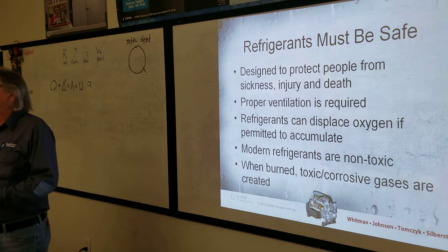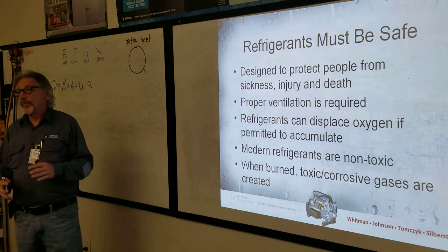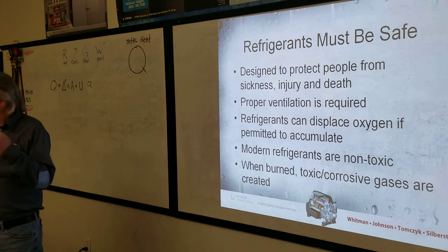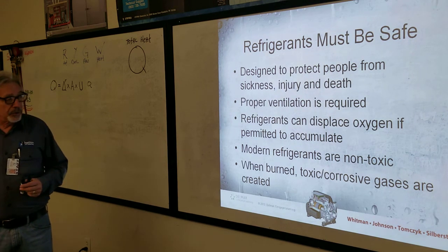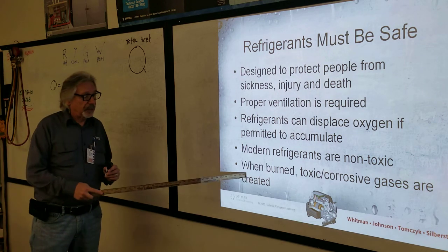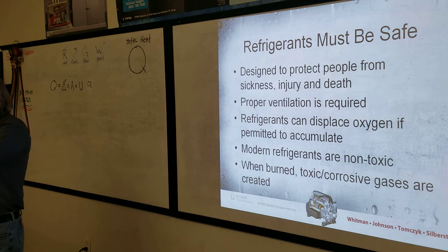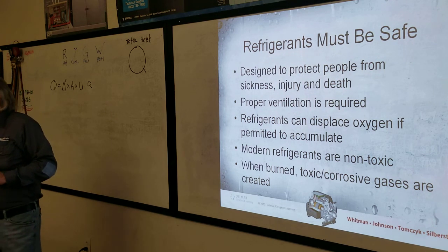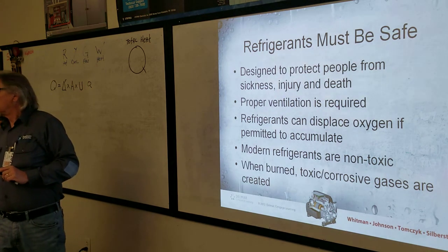If you're unsweating a compressor or something like that, and there's residual refrigerant in there, you could be burning some refrigerant as it starts to come out. So the toxic corrosive gas that is created is phosgene gas. You ever heard of phosgene? Phosgene gas was a chemical weapon used in World War I.